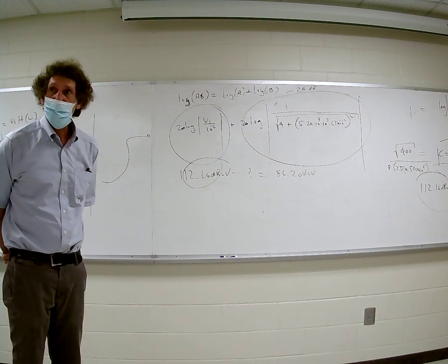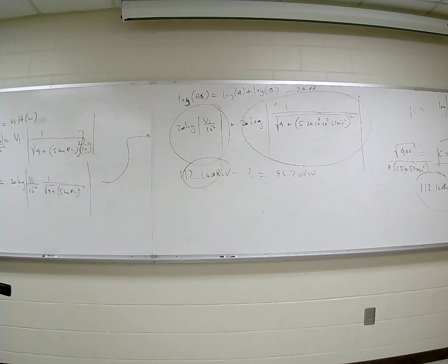Now, there's a lot of people who make mistakes along the way on a problem like this. But I hope I showed you how to think about it. Always look at the value of the input signal at the frequency, 5th harmonic, 6th, 7th, 8th. Then find the reduction at that frequency the filter causes. All right? You with me?